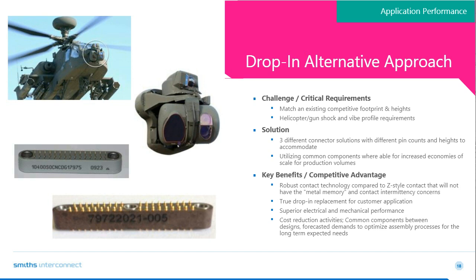The solution had Smith replacing the competing bent metal style contact technology that exhibits the known metal memory problems that come from being in a mated condition for long extended periods of time, which was the root cause of the customer's issue. Again, utilizing the actual coil spring eliminates the concerns of extended life in a compressed state and dropping signals during the environmental exposures.